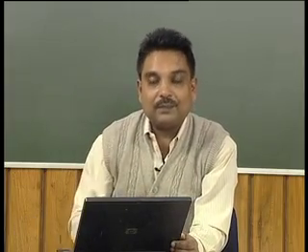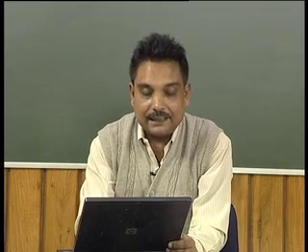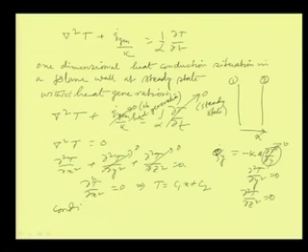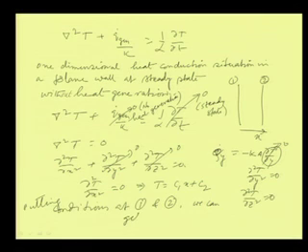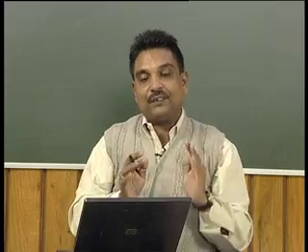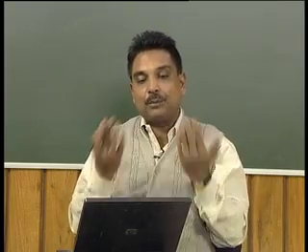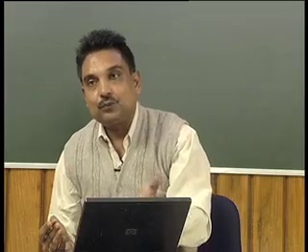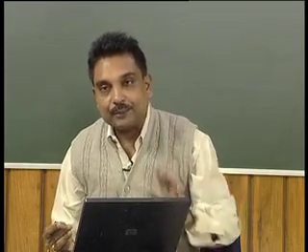And we can find out the values of C 1 and C 2 based on the conditions at station 1 and station 2. Putting conditions at stations 1 and 2, we can get the C 1 and C 2 values. So, this is the way we can simplify, starting from the conduction equation. For any problem given to us, we can simplify these for getting a temperature profile.